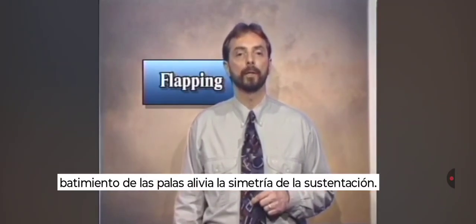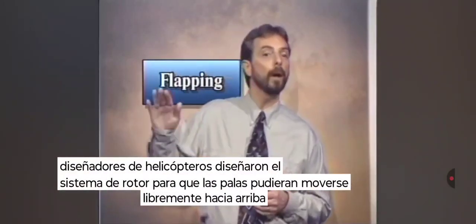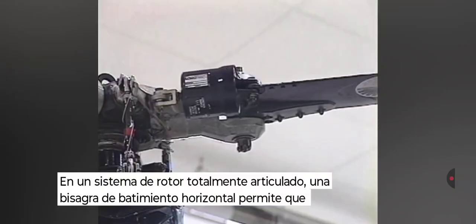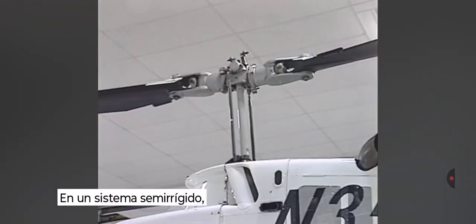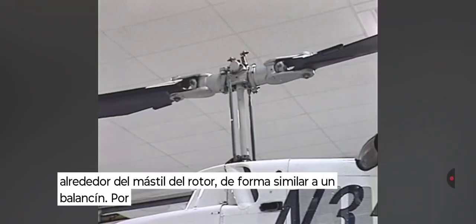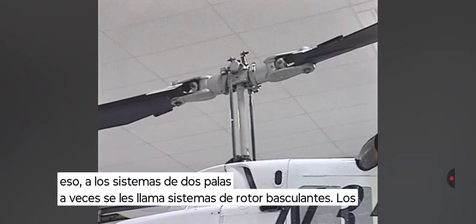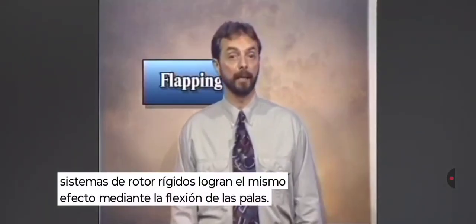Flapping alleviates dissymmetry of lift. Rotorcraft designers designed the rotor system so that the blades can move up and down freely. In a fully articulated rotor system, a horizontal flapping hinge allows each blade to move up and down independently. In a semi-rigid system, the blades move up and down as a unit about the rotor mast, much like a teeter-totter. This is why two-bladed systems are sometimes called teetering rotor systems. Rigid rotor systems achieve the same effect by way of blade bending.